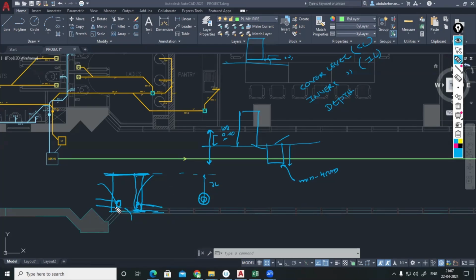Anyhow, between the inlet and outlet, different standards are there. Minimum 5 centimeter. Few standards are suggesting 50 centimeter. But if you are considering 50 centimeter and you are having more number of manholes, accordingly the depth of manhole will be increasing. Because 5 centimeter extra depth if you are considering, the next manhole will come to 10 centimeter. If you are having 3 manholes in the series, the depth will be increasing by 30 centimeters. That's why you can consider just 1 or 2 centimeter, or 10 to 20 mm, which is more than fine. So when we are doing that, you'll be getting a clear idea.